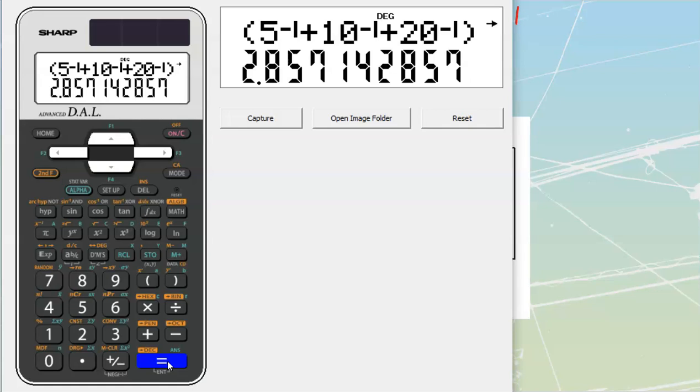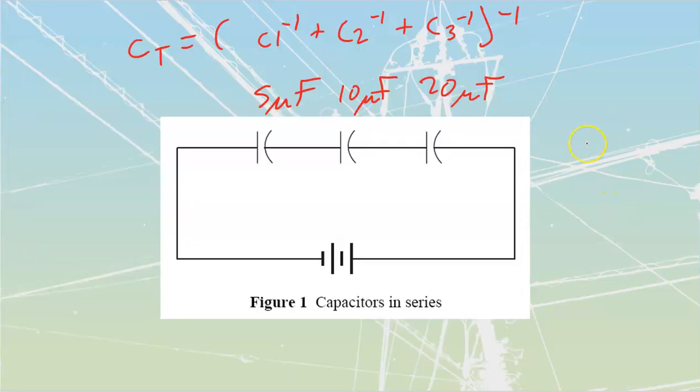What they're doing on theirs is they are just adding together all of the bottoms to form that, 1 over top of CT. So they're adding in 1/5 plus 1/10 plus 1/20 to equal this, 1 over 0.35 that they have over there. The math doesn't make sense the way that they present it. I'm not too concerned about trying to correct their math, though, because this is the way that we do these things on a calculator. We punch them in with the -1 to the -1 to the -1, and then we re-invert the entire shooting match. So this one would become 2.85.